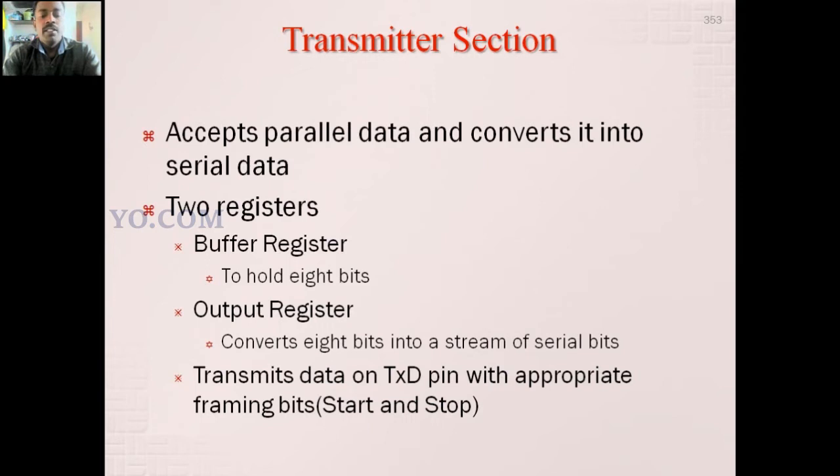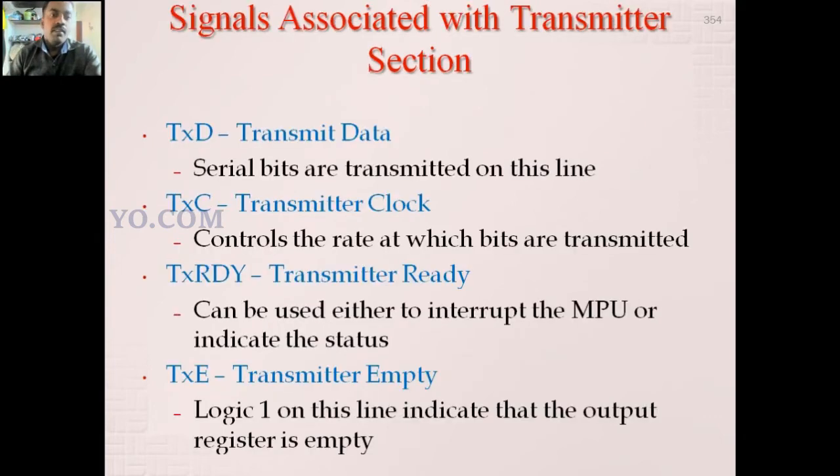Okay, it transmits data on the TXD pin with appropriate framing bits, start bit and stop bit, because serial data transfer is only by frames. So each frame contains some data bits, then start bit, stop bit, parity bit, etc. Okay, right.